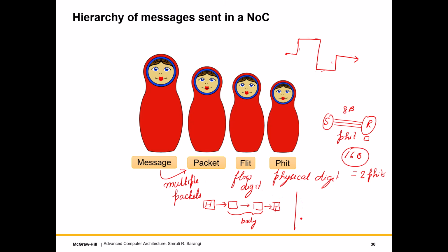The most important difference between a regular network and an on-chip network is that you are not allowed to drop packets. Let me write this, it is so important. It is a given that it is not allowed to drop packets. Philosophically, this is a marked departure from a regular network, because in a regular network, we drop packets. That is how you figure out there is congestion and then you do something. But in the case of an on-chip network, packet dropping is absolutely not allowed.